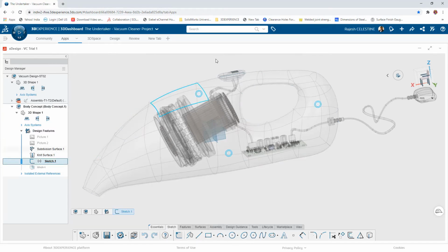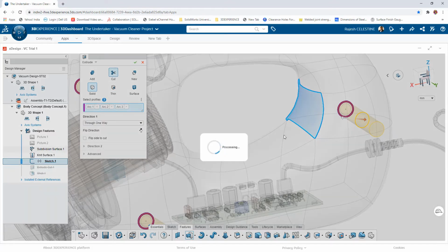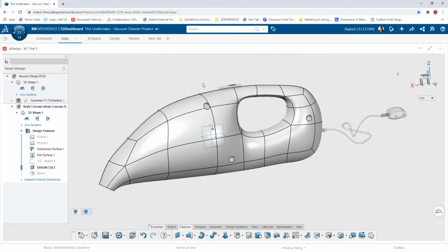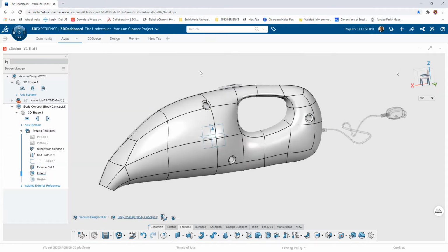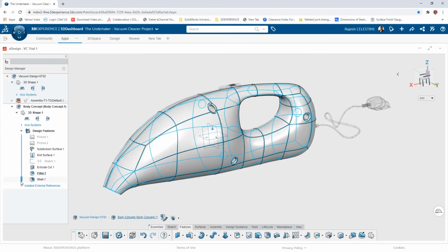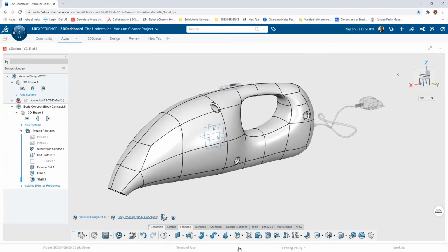After completing, I apply the extrude feature to remove material from the geometry. Applying a radius of 2 mm on the edges of the boss completes it. Now, drag the rollback bar to activate the shell feature. Let me now proceed to split the bodies.